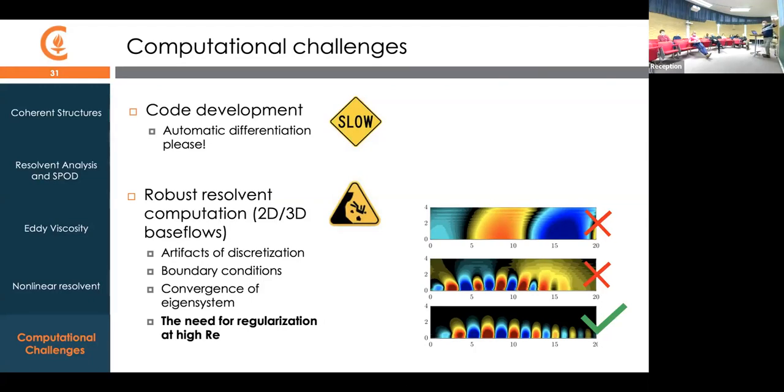So you need grids that are probably even finer than a DNS grid to get good resolvent calculations for those. It's certainly possible to do this for flows that Beverly has considered, channel flows with one homogeneous direction. This is not so much of a problem because we can use lots of grid points in one direction. You can get really good, sort of asymptotically high Reynolds number results there. That's difficult to do for these flows.